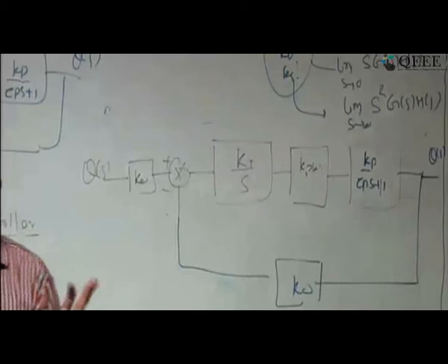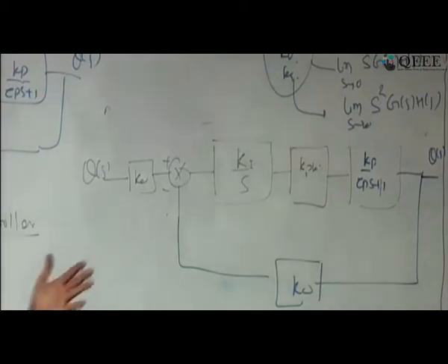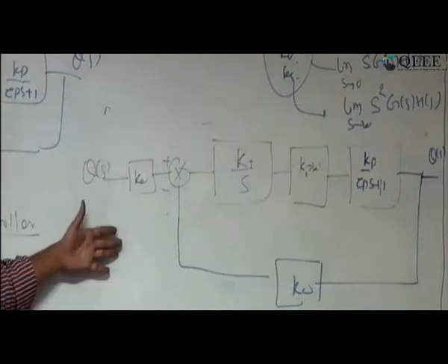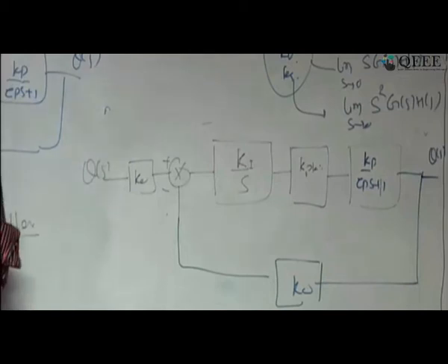Okay, are these two parts clear? In a proportional controller, you are making your system fast, that we have seen, but you are not getting a steady state value of 1. In an integral controller, you are adding a term that increases the type of the system, hence it helps you achieve a steady state error of 0.